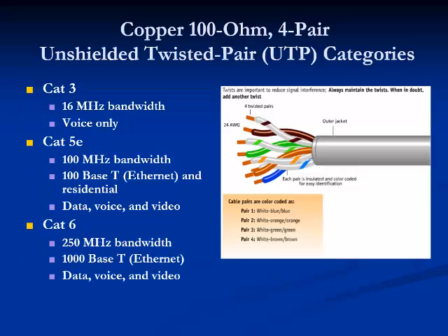The TIA 568B.1 specifies performance requirements for unshielded twisted pair cabling, shielded twisted pair, and fiber optic cabling. Further, specifications are laid out for length of cable and conductor types for horizontal cabling, the backbone, and patch cords. The standard specifies 3 categories of UTP cable to be used with structured cabling systems.